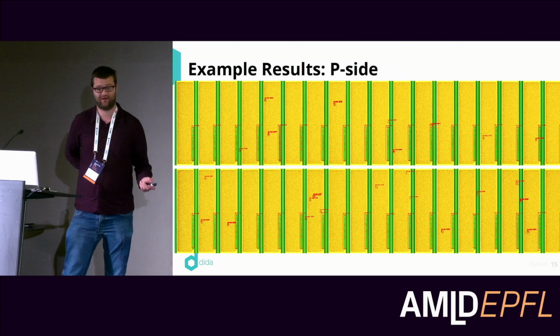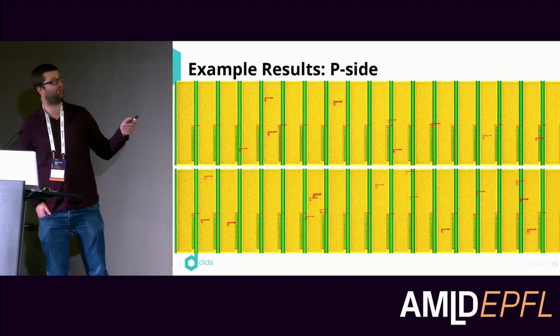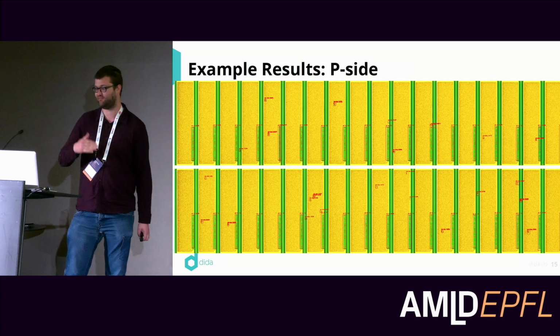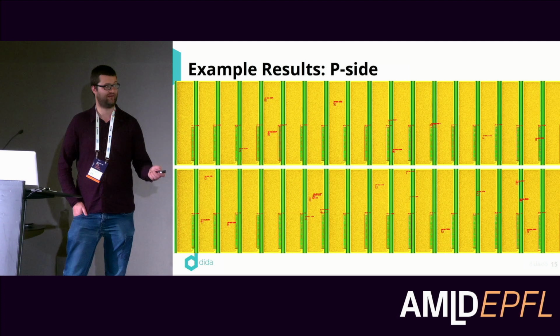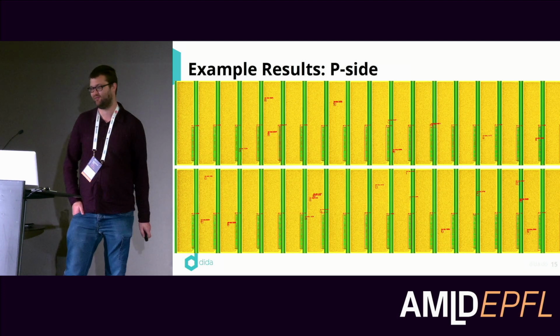I think the main uses for this are to help a human quality assurance person rather than replace them, and also to help get statistics on the errors. For example, these small ones are dots, and if there are too many of those, that's an indication that the temperature of the furnace is too high. So even if you're not necessarily using this as a gating step, there's an advantage to automating it because it lets you look at these statistics more easily rather than having to go through and label them. It's easy to look at this and see that this one is not usable, but a human would have to label all of them if you really want to look at the statistics.